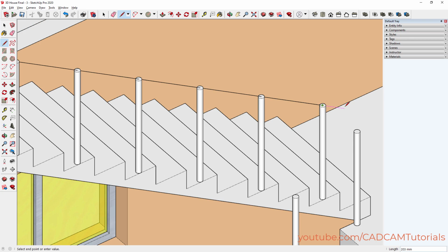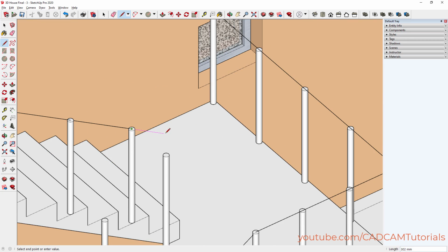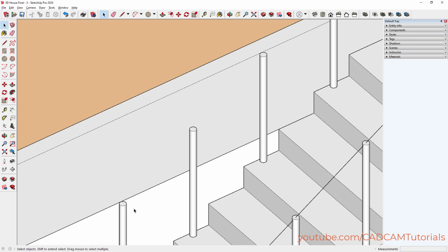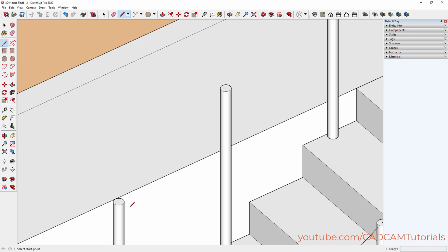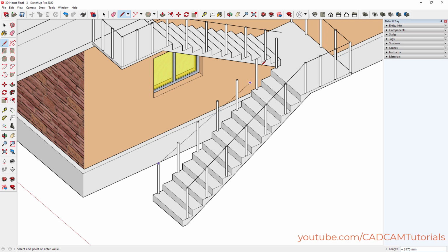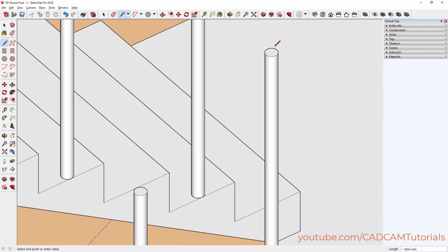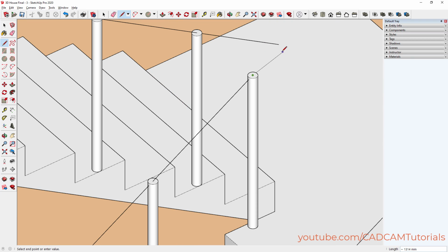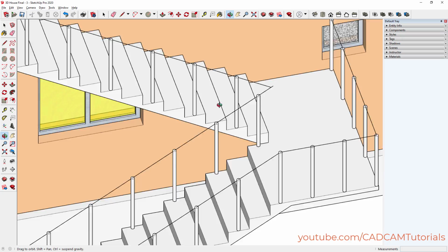Take it below in pink direction, that is extend edge. Click, press spacebar on this bottom pipe. Click on lines. Take your cursor on this circle, take it inside, click at center. And click on the center of top pipe. Okay, we will extend it outside in pink direction. Press spacebar. Then zoom here.